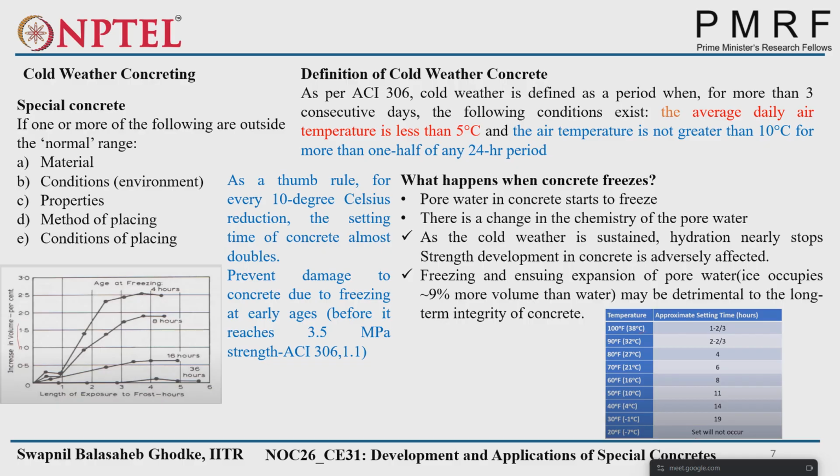Yeah, initial setting time. Because I already said most of the care we have to take is only for the initial phases of hydration. If you see this plot also, initial phases affect more. So for that purpose, this is given for initial setting time only. And a thumb rule is given. According to the thumb rule, if there is a 10 degree Celsius reduction in temperature, the setting time of concrete almost doubles.